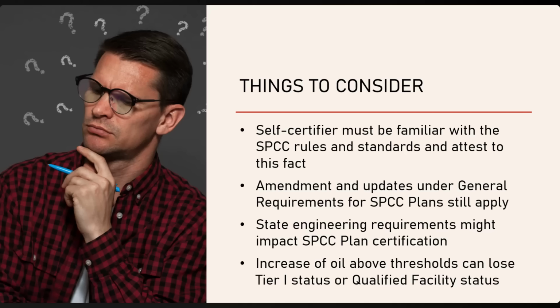State engineering requirements might impact the SPCC plan certification. Some states require a PE to perform certain functions, including certifying SPCC plans. Check with your state's engineering licensing board to find out if it prohibits SPCC plan self-certification. Lastly, an increase of oil above thresholds can lose the Tier 1 status and qualified facility status. Therefore, any benefits resulting from the qualified facility options might be temporary.